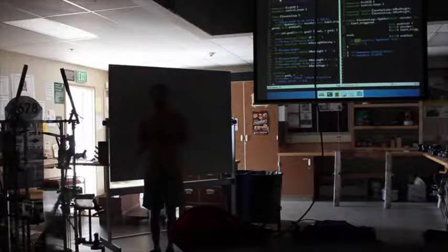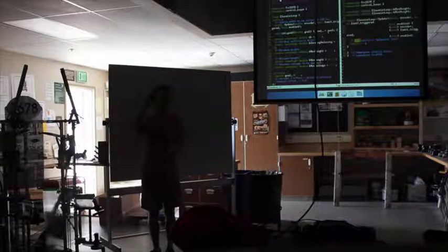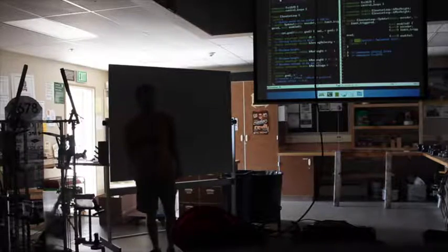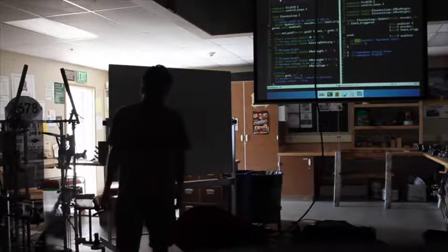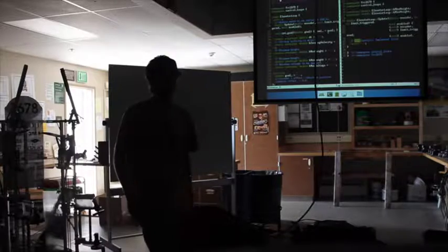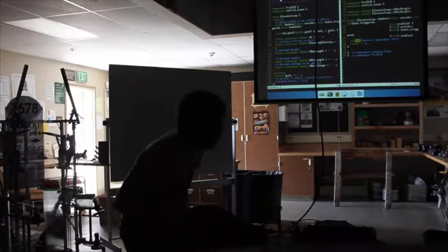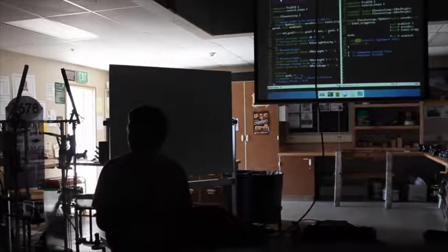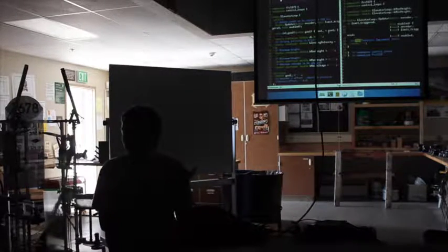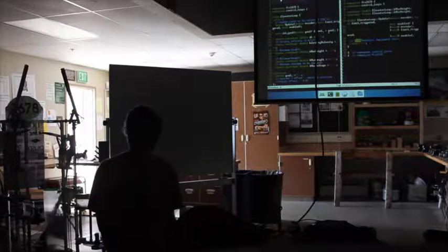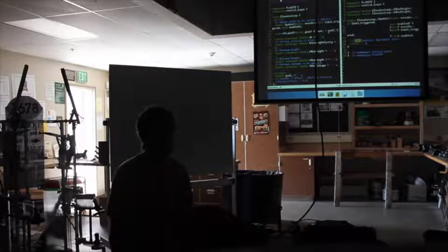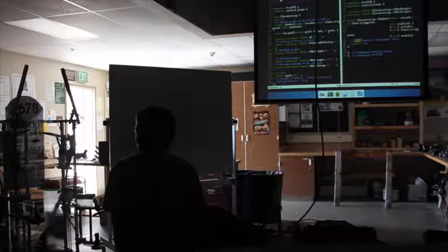The way to do that is you move until you find 0, and then you look at what the encoder read at that point, which will be the distance from where you started, and then you subtract that out all the time, and then you're good. So we need to compute that offset so that we can zero. Ideally, you subtract that once and put it in a value, and then it automatically gets subtracted. Yes, it's just designing your software to be robust in that way so that people can't accidentally get an unadjusted value.